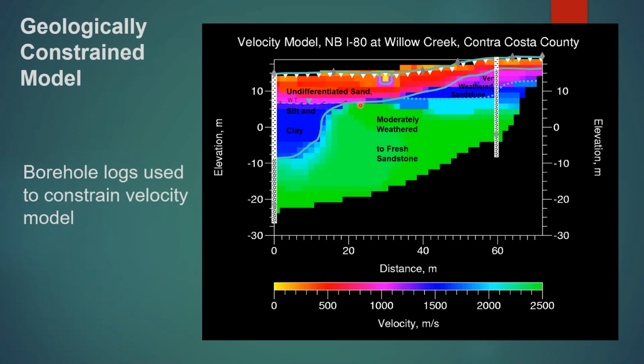And most notable is that we see that the sandstone is not at a constant dip. And indeed, what we have here is an erosional bank from channelization of a Pleistocene paleo channel. And at least that's what we believe it is. We don't believe it's fault controlled. So that was a good example of how we can use this borehole information along with these borehole sources to develop these different models.